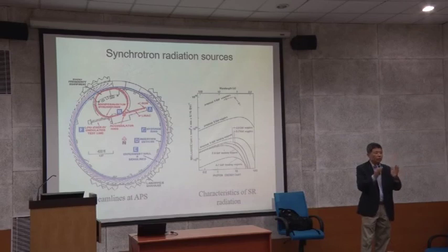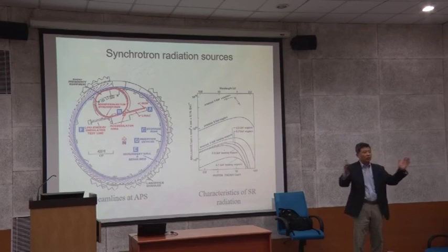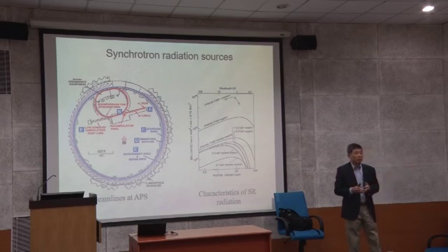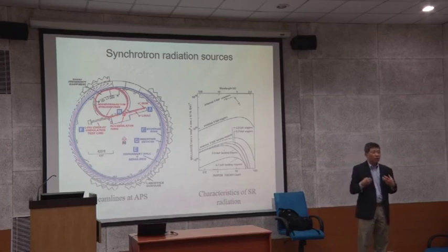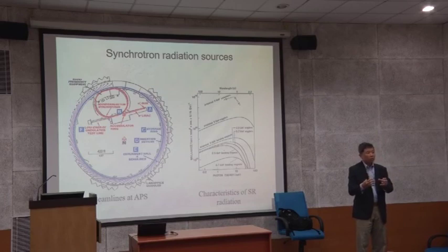Okay, so now I talk about the X-ray source. You have 3 different X-ray sources, and wavelengths can be varied over a wide range by synchrotron, but the X-ray source we use in the lab, most of you working on inorganic materials, I think is the copper K line, which is 1.54 angstrom, and that's the source for materials. And the next thing is X-ray diffraction is an interaction between this X-ray and your material. So that's the basic interaction.